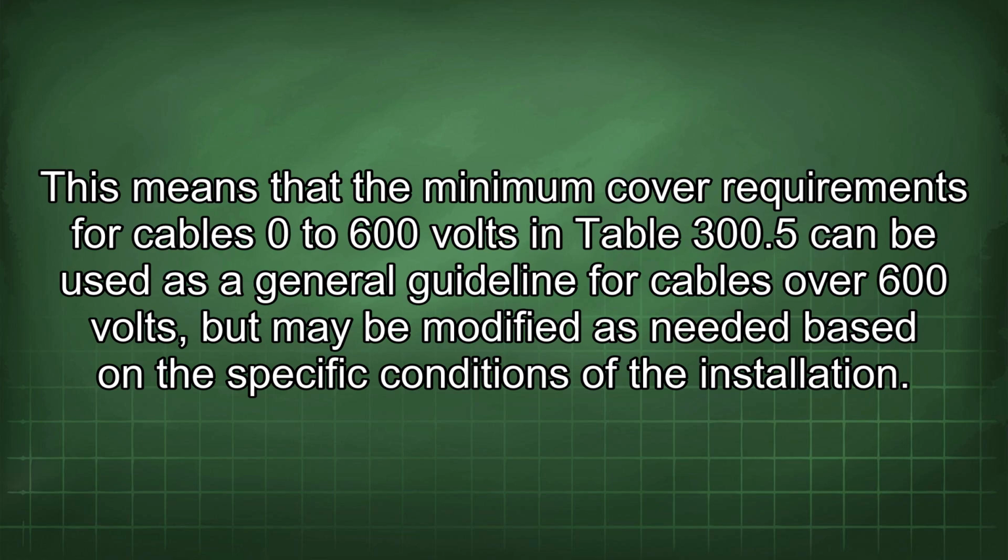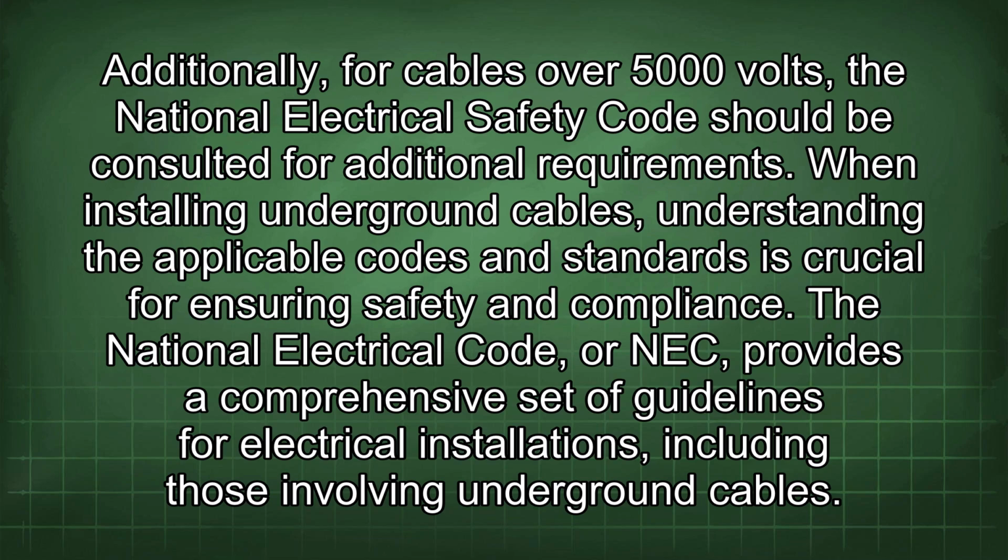a general guideline for cables over 600 volts, but may be modified as needed based on the specific conditions of the installation. Additionally, for cables over 5,000 volts, the National Electrical Safety Code should be consulted for additional requirements. When installing underground cables, understanding the applicable codes and standards is crucial for ensuring safety and compliance.